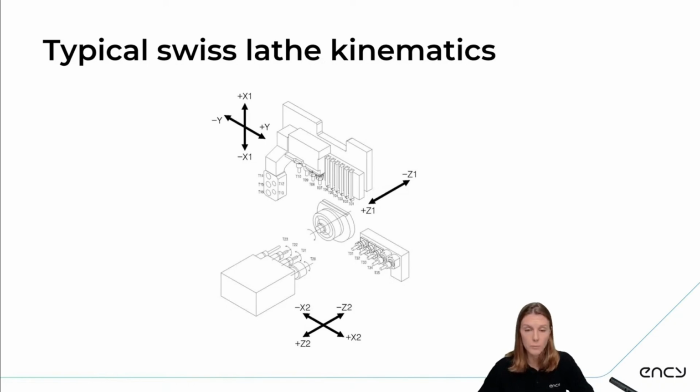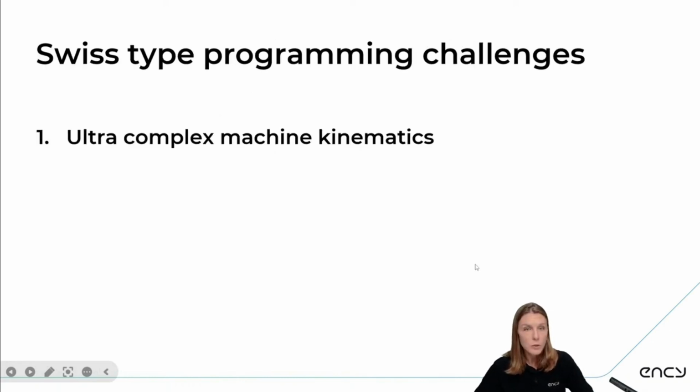And how can we program all of these axes, gangs, and spindles? How can we make the programming of these machines fast and efficient? We also asked ourselves what challenges a Swiss lathe programmer has in front of him. For sure, it's quite complex machine kinematics, so it could be 10 or even more programming axes.